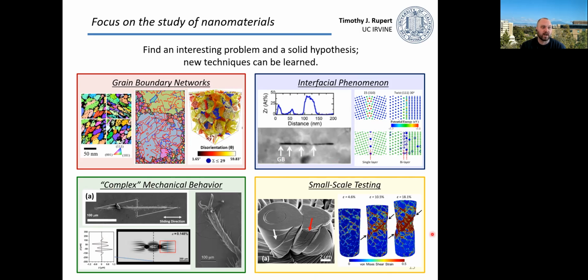We also do a lot of mechanical testing. Some of it is basically the same version of how we would normally compress and pull on materials, but on the micro scale. This is showing a little compression test, but this pillar is only about 4 microns wide. For reference, a piece of hair on your head is about 100 microns wide.